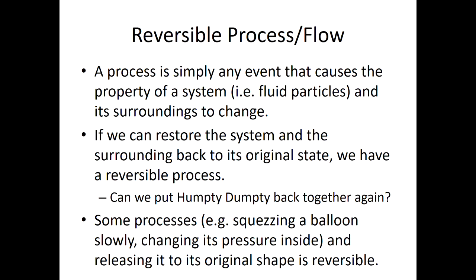But what happens if we have a shock wave? When the molecule crosses the shock wave, it goes through an irreversible change. Entropy rises. Stagnation temperature remains constant, as we saw earlier. But because the entropy goes up, some of the other properties, such as the stagnation pressure, decrease. So properties cannot be put back into their original state. Then you have an irreversible process. Flow through a shock wave is a prime example of an irreversible process. Boundary layer flows, anything that is viscous, is an irreversible process.